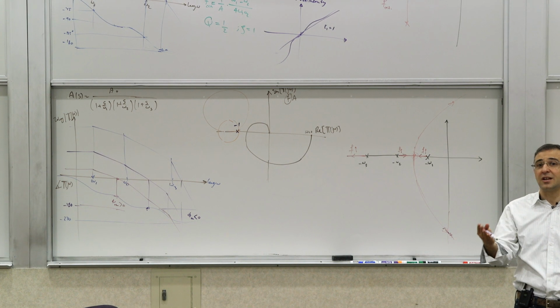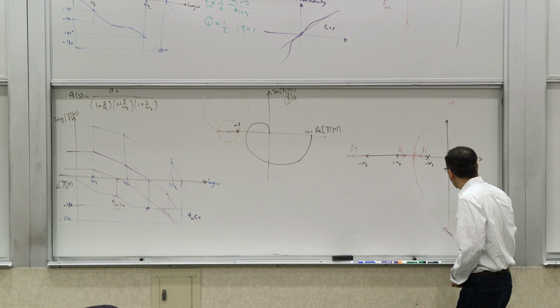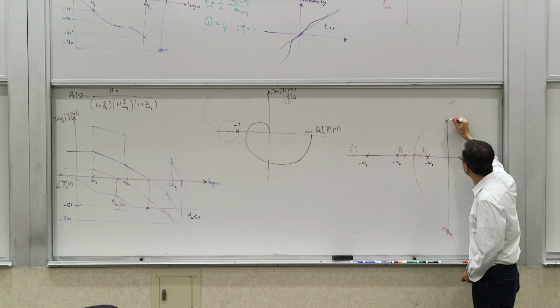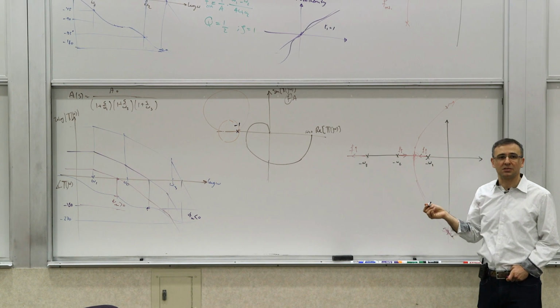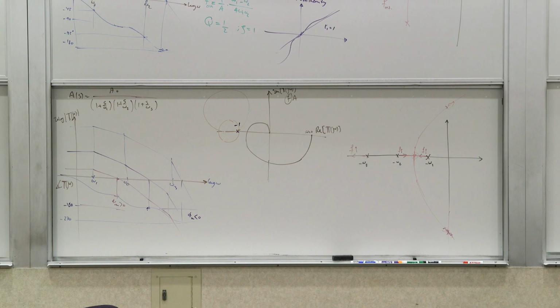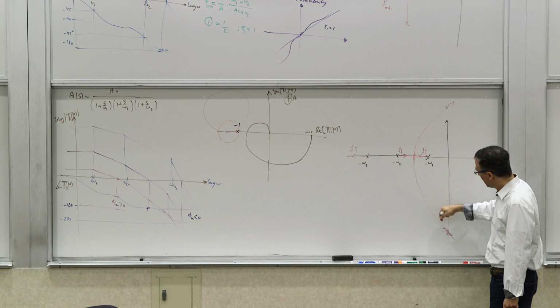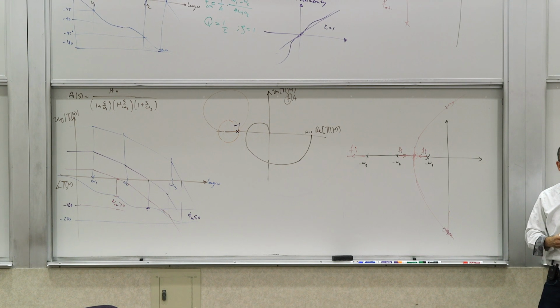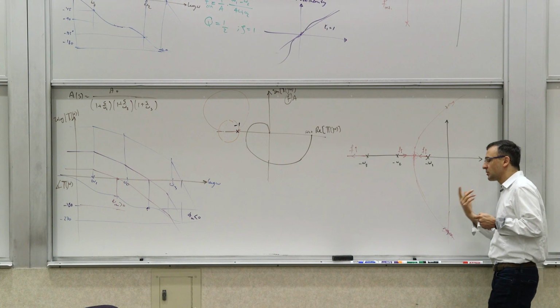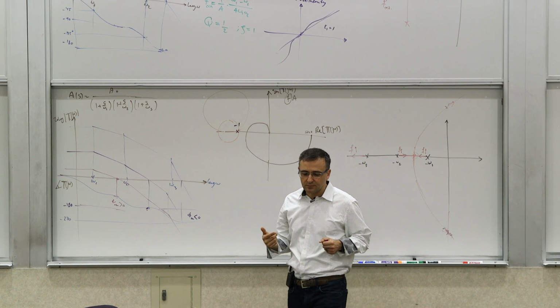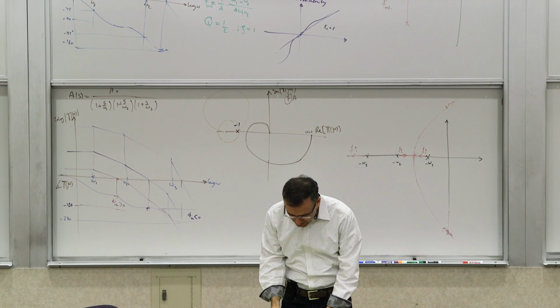And that's not actually about using the nonlinearity. We briefly talked about this, and we can talk about it a little bit more, about the amplitude stabilizing mechanisms in an oscillator. But that's what they do. They push it back this way if it goes that way, and the other way around. So it maintains it exactly on the j omega axis, and that's how you make an oscillator. We'll talk a little bit more about that later. But that's the essence of this thing.